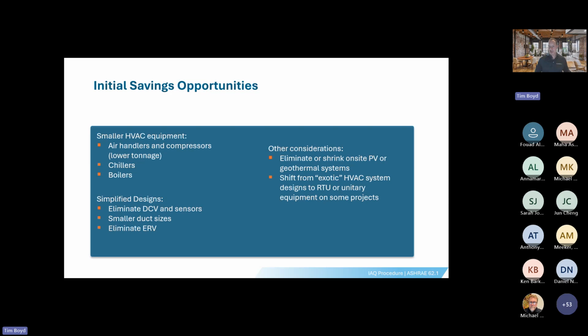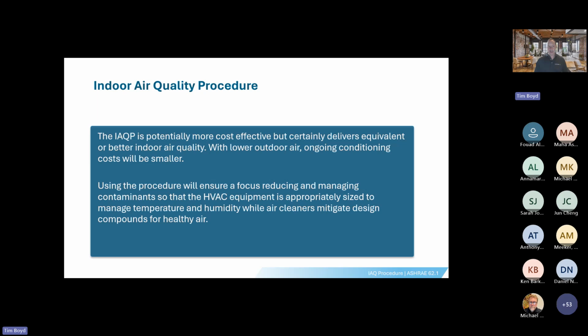So again, significant savings. There are some other considerations, which I'm not going to go into, but I think those examples really highlight how valuable the indoor air quality procedure is and why you can see ASHRAE has really started to move this into the forefront of their methodology. If done properly, you get better cleaned air, you can lower your outdoor air, and obviously get all those cost benefits that we talked about, on both the operating and first cost side.